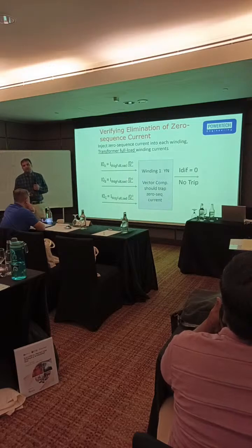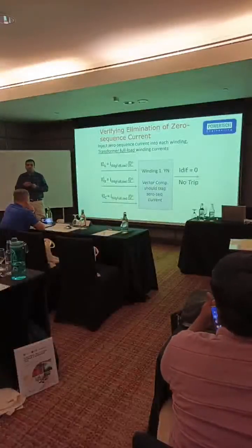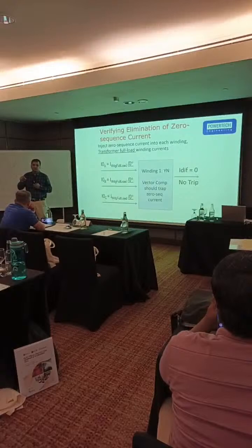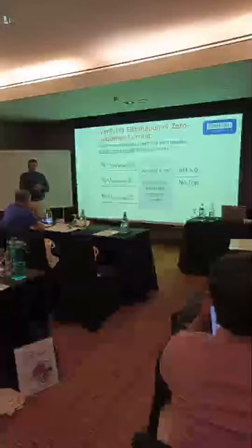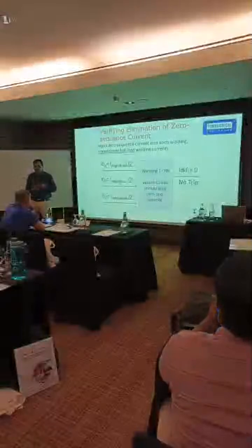How can you understand this? If you know how to calculate zero sequence current from phase current, you just put that formula. Then you will find that if we add all phasor currents, then the sum will be the zero sequence current. No positive or negative sequence current.